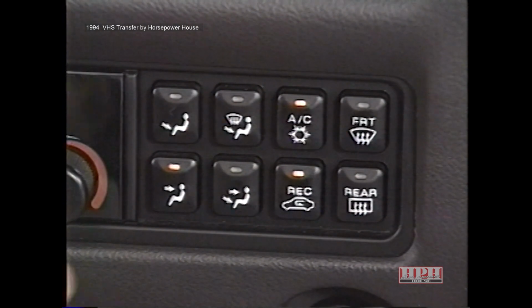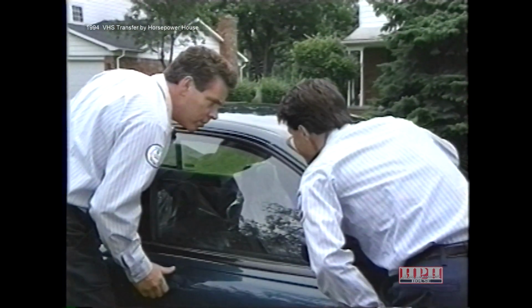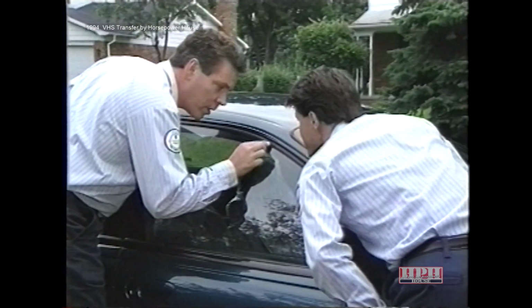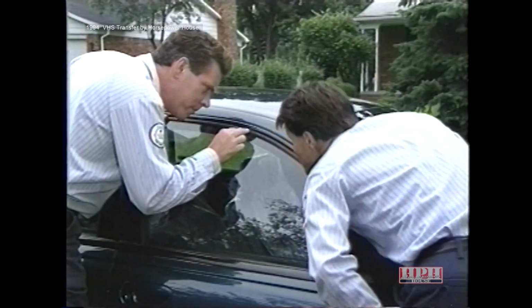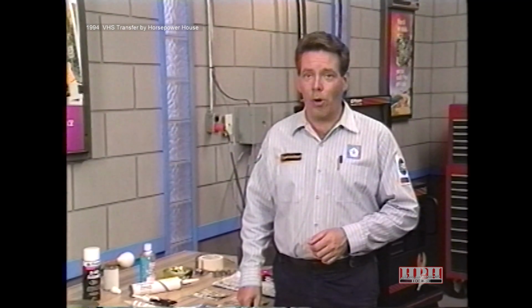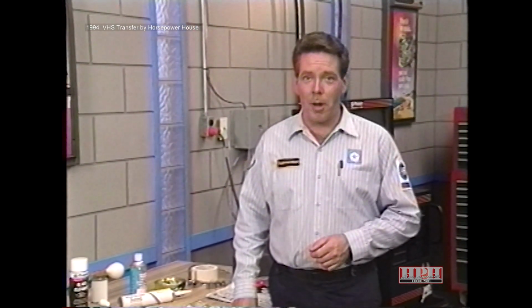Opening the fresh air inlet doors to pressurize the interior may cause the noise to become louder and make diagnosis easier. Once you've determined the approximate leak location, pull the vehicle over and inspect the problem area. If you can see the problem, make the repair using the tools you took on the test drive. Or if a simple repair cannot be performed, return to the shop to fix the problem.